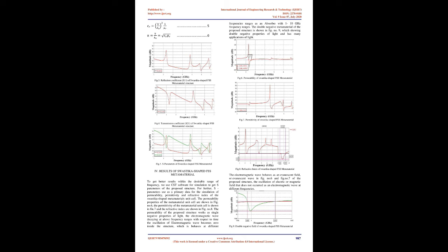In electromagnetics, the material's characteristics are defined by the permittivity, permeability, and conductivity. The propagation profile of the material at a different frequency is defined by the extraction of permittivity and permeability at that frequency. To extract the permittivity and permeability of the material, the refractive index and impedance of the material are used. To extract permittivity and permeability, consider the unit element of a metamaterial with lattice vectors in all 3 dimensions.